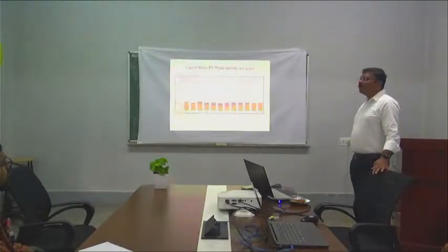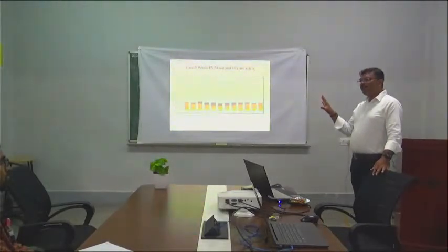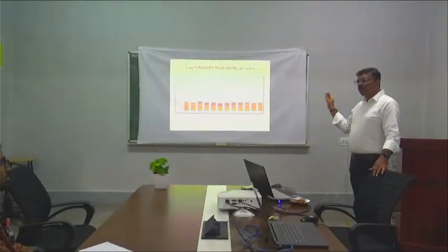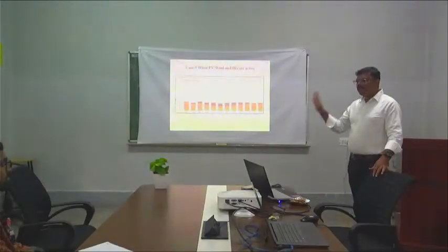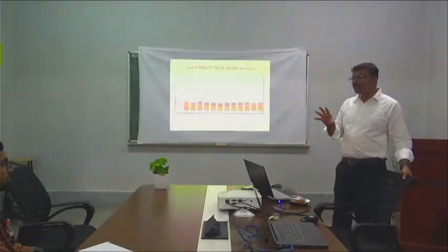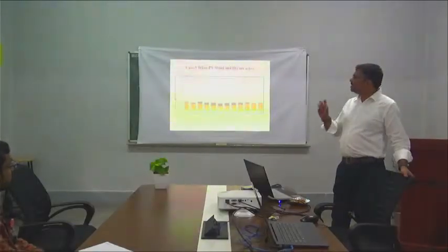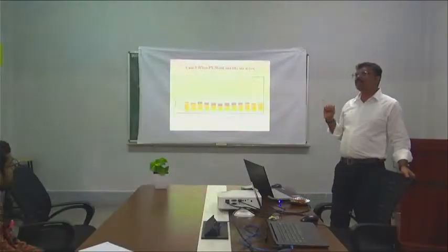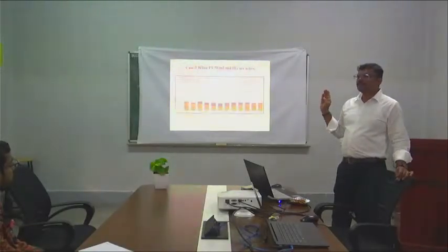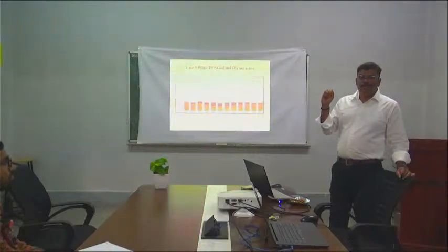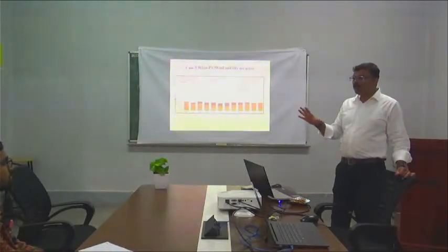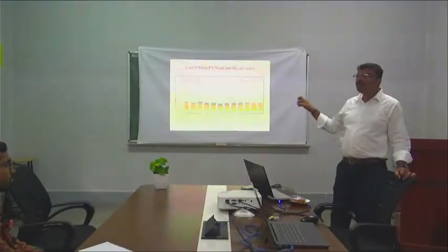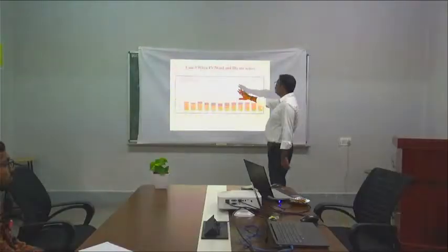Obviously, when you want to optimize this scenario, when the power produced by solar PV and wind is equal to load plus losses, DG will be in idle position, correct? Obviously the algorithm will work like that only. But still, if you see how much energy is generated from the diesel generator in this case, approximately 75,000. That means if you want to operate your system with only solar and wind, you need to have a DG to supply this particular load demand.